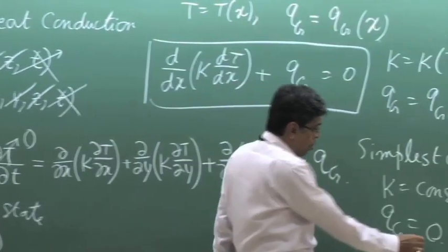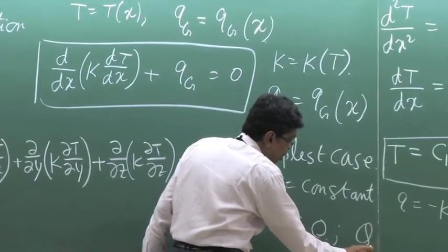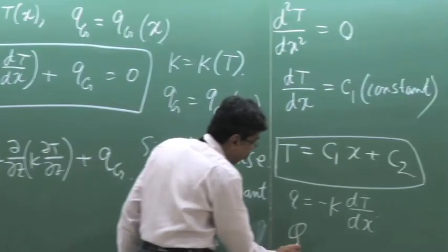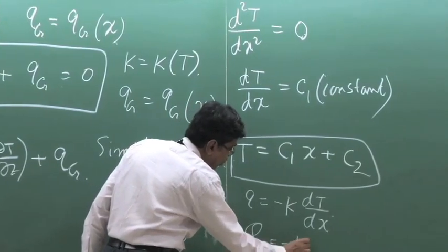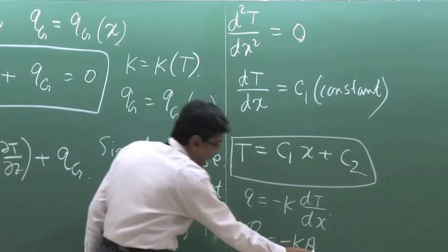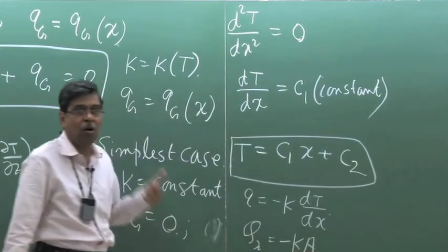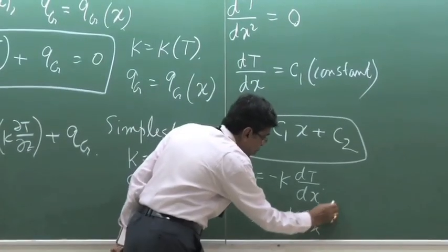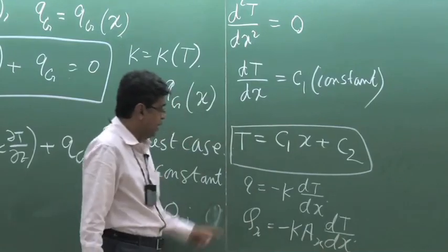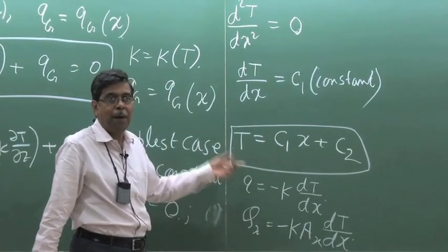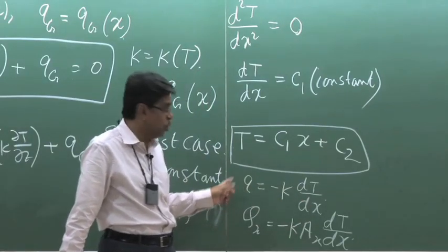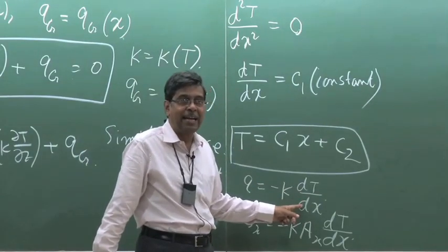And if we find the heat flux over an area, then we multiply with the area A. I write Ax, meaning the area normal to the x coordinate, but this x is not required because the heat flux is defined per unit area normal to the direction of heat flow, and heat flux is proportional to the temperature gradient along this direction.